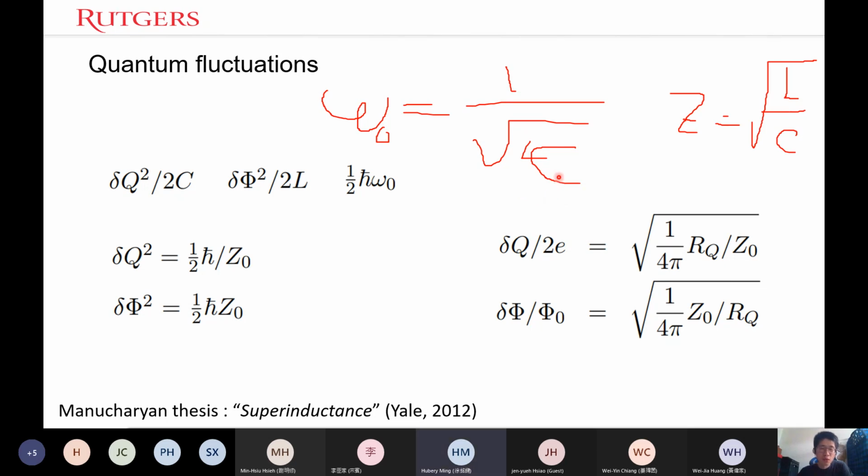I see. So from an engineering point of view, we need to provide some element that still functions when we are using our qubit. For example, if the qubit frequency is 5 gigahertz, the circuit element we are proposing needs to still work as intended, for example as a resonator, at that frequency.